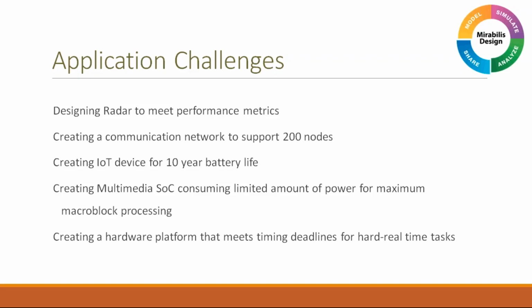It could be creating an IoT device architecture which can sustain about 10 years of battery life, so how you can architect your IoT system platform to meet your power requirements. And you could design a multimedia SoC platform to meet your performance versus power trade-off and all the requirements such as macro block processing.